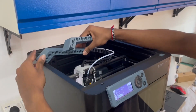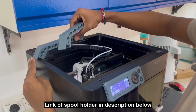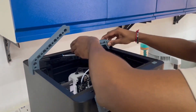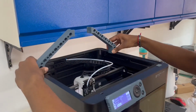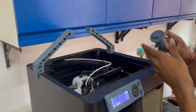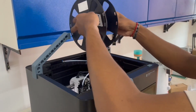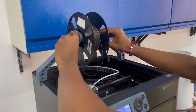So as you can see, I'm attaching a top mount to hold the filament. Why am I doing this? It's because this MRE filament is flexible and has lower hardness. So over here, I'm going to insert this into the filament and then directly mount it on top.